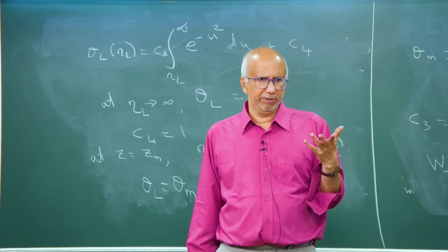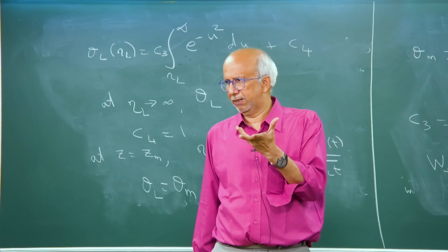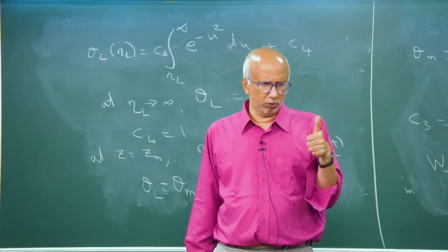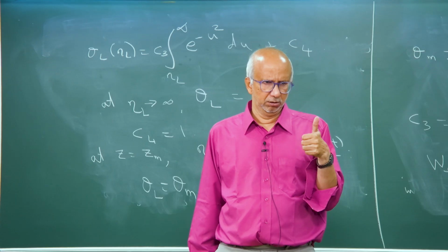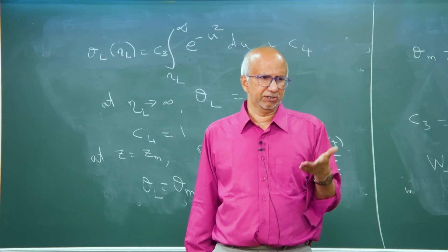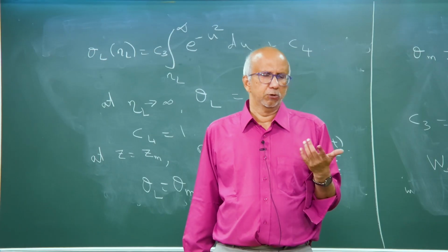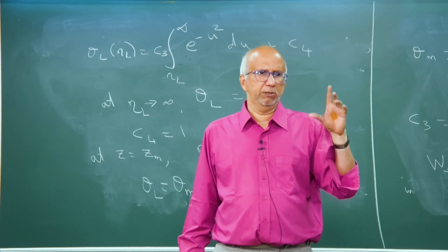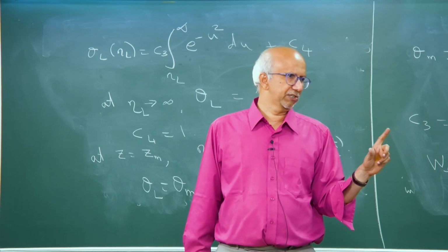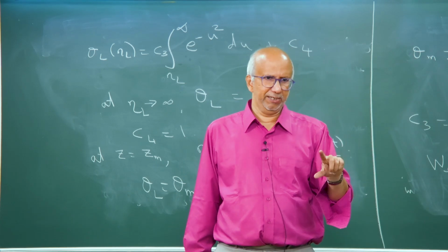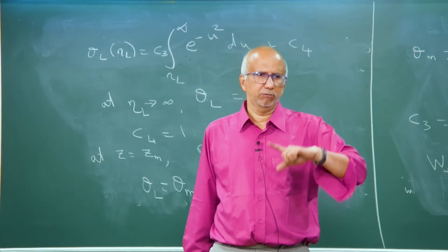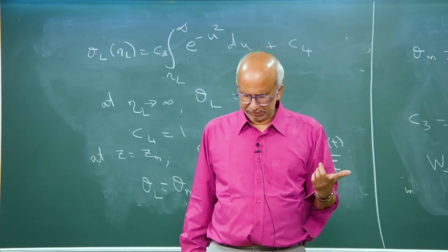Okay. I am yet to find out that constant beta that I spoke about earlier. How do I find that out? There is one more condition which I have not used, which is the heat flux condition. Basically, you have found the theta S and the theta L, you go to the heat flux condition, you substitute this theta S and theta L there and find the beta, find how Z is changing with time. Okay. That is the idea.